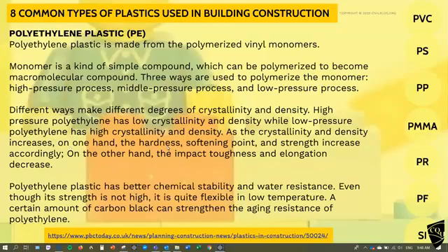It's got some hardness, it softens very easily under temperature, but as you soften it and as the temperature goes up, the strength does increase. However, as it gets a bit warmer, its impact toughness drops and its elongation will decrease, it'll snap. You tend to find that this particular plastic, although it's flexible in low temperatures, has been used for pipes and things like that, but it's more in plastic sheets nowadays.